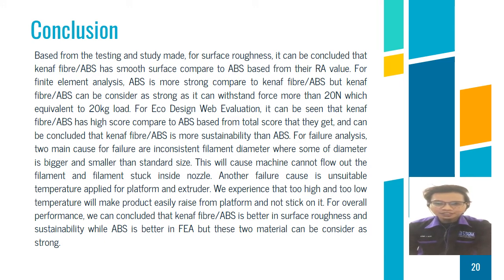For the FEA analysis, we can see that ABS is stronger compared to kenaf fiber ABS, but kenaf fiber ABS can also be considered strong because it can withstand 200 Newton of force, and starts to deform after we apply 300 Newton of force. This difference is because of their slightly different yield strength.